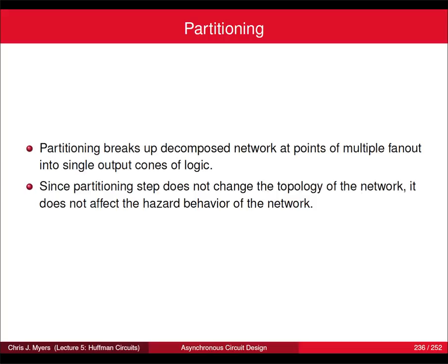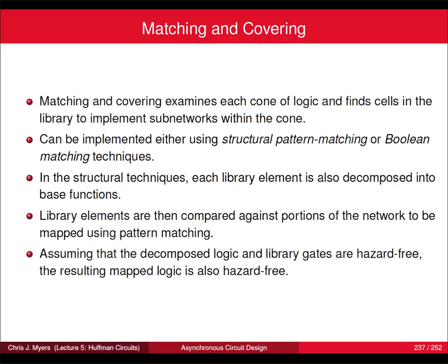The next step is partitioning. And partitioning, what it does is it takes any multi-output function and breaks it down into single output cones of logic. It's sort of a divide and conquer approach. Since partitioning doesn't change the topology of the network, it doesn't affect the hazard behavior. So partitioning is completely legal as well.